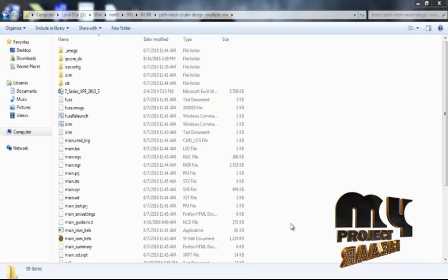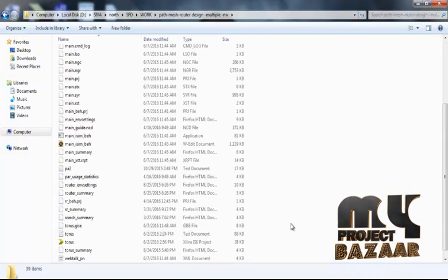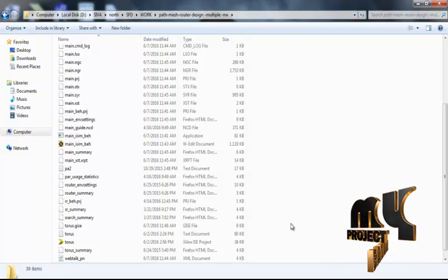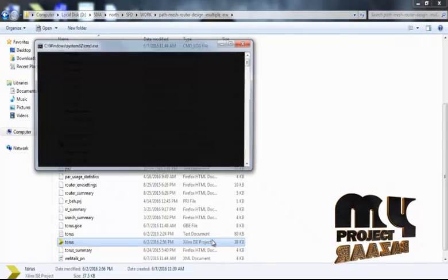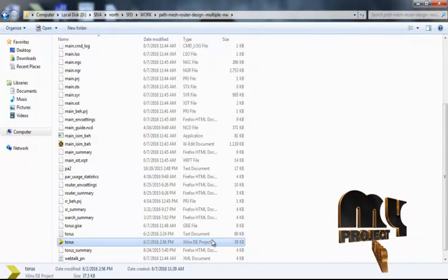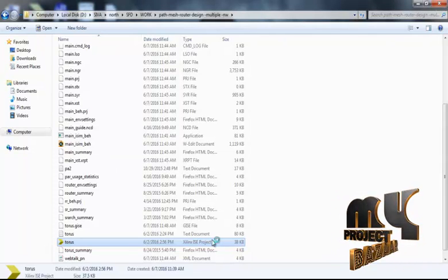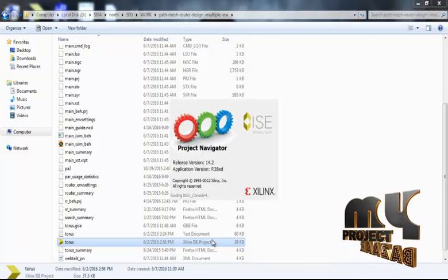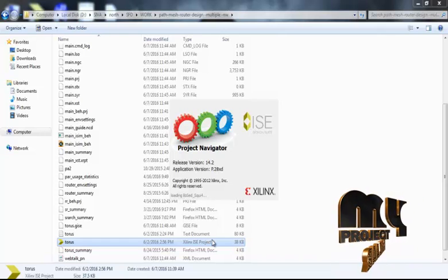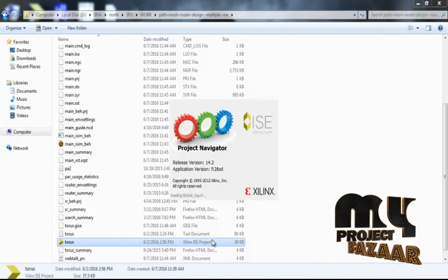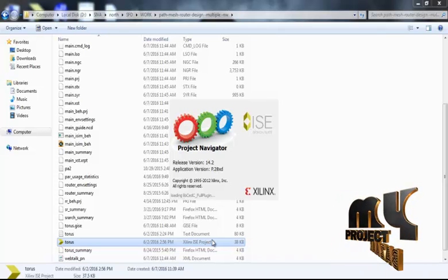Finally, we see the output for the product. We developed our project in Xilinx software, and we use VHDL code for our required NOC type of projects. We implement the project based on on-chip and off-chip communication. So we develop the single router architecture. Each single router architecture consists of the injection and ejection operation, the router section and the crossbar section. The crossbar section is mainly focused on the round robin based methodology.